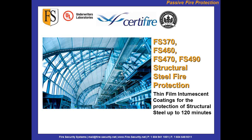So we have 4 versions of structural steel coating, soon to be 5 with a hydrocarbon coating, but I'll get to that a bit later. So please remind me before we finish. We have FS 370, FS 460, 470, and 490. All 4 are thin film coatings for the protection of structural steel up to 120 minutes or 2 hours. And each of these members, 370, 460, and 470, are British Standard approved, 490 is UL approved.